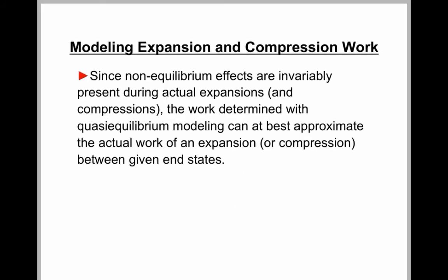Naturally, if we are talking about some type of engine running at 5,000 RPM, you're going to certainly get non-equilibrium effects taking place. However, the initial assumption of saying that I am at a given pressure at state 1 to another pressure at state 2 is reasonable for first order estimates of the work.